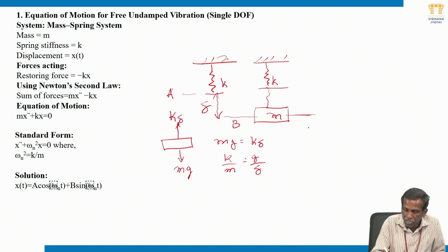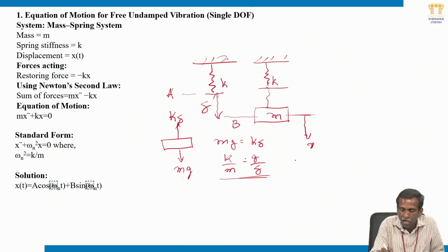So this is the basic equation of free undamped vibrations; keep it aside. If you displace the mass further, some extra displacement x downward, then it is going to start oscillations, down and up, down and up. You have given x displacement downward, disturbed it and left it. Because it will oscillate, you can see velocity and acceleration due to this x.